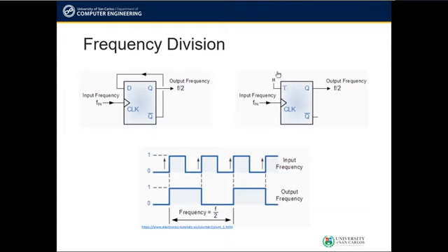What happens on the T flip-flop is that at every active edge detected at the clock input, in this example again the rising edge as shown by the upward pointing arrow, the output would simply shift high and low continuously since the T input is high for the T flip-flop.